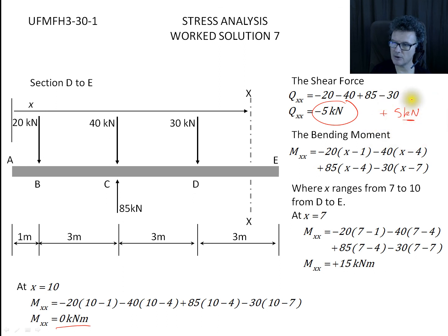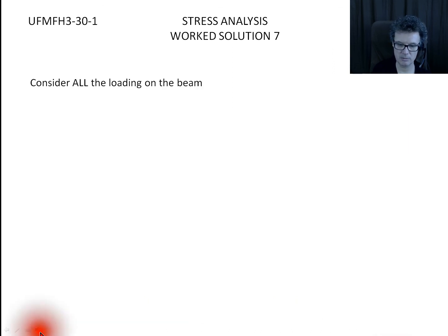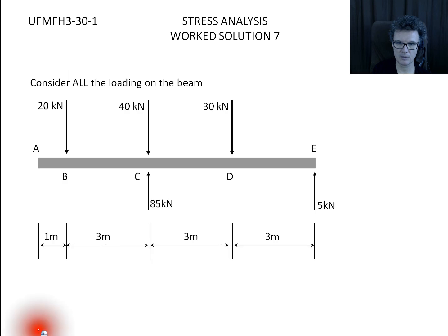So that would then tell us that when I sum up all my forces in the y direction, they equal 0, and when I get to the end of the beam and sum up my turning moments, they will equal 0. So when you introduce the final bit, that upward force there, you can see that your forces will sum up to be 0.